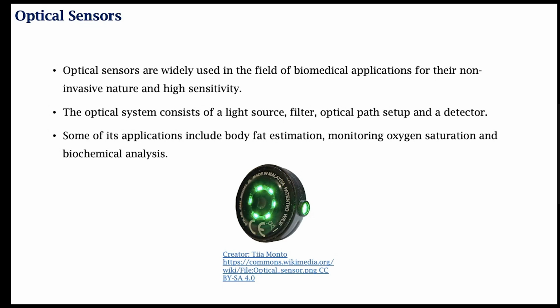And then we looked at capacitive sensors that essentially exploit the epsilon A by D principle, in which one plate is a diaphragm that can deform, and the change in capacitance can be measured as a change in voltage across that capacitance, for example. Then we looked at inductive sensors. In particular, we focused a lot on LVDT, linear variable differential transformer type devices, and we discussed how these can be miniaturized and what are the various applications of these.